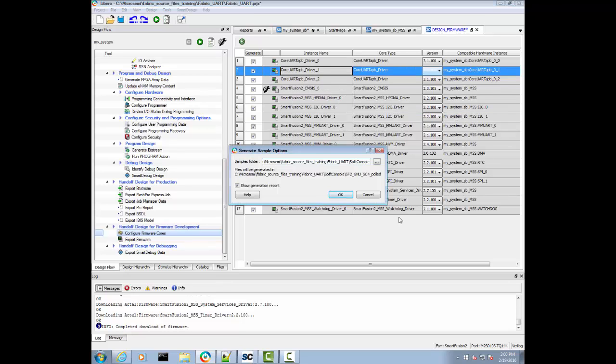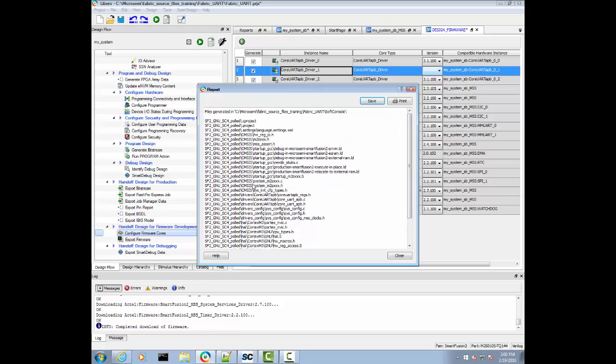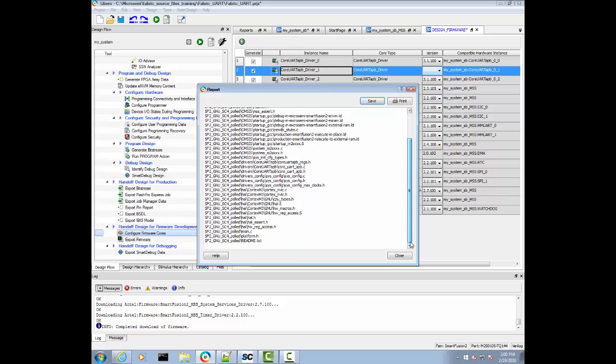I'll just choose hold transmit, okay? This will create a folder called SoftConsole under our project here, and it's going to create a little project that has a SimSys, it has drivers, it has the HAL. In the SimSys, it's going to have those linker scripts. It has a little main.c. It has a platform.h, but I'll show you a gotcha about that. Okay, well, hang on a second.